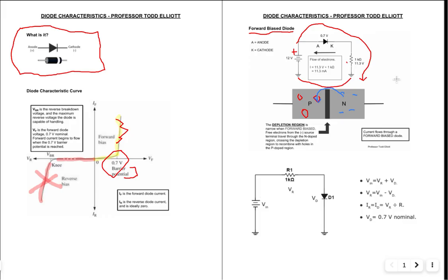It's doped to have free electrons, which will be enough to kick that electron up out of the valence band into the conduction energy band, where it will go through the barrier, the depletion region, and then it will lose its energy, recombine, fall into a hole in the P region, and exit the P region to become the current, to complete the current path. Okay. All right. So that is essentially how it works.